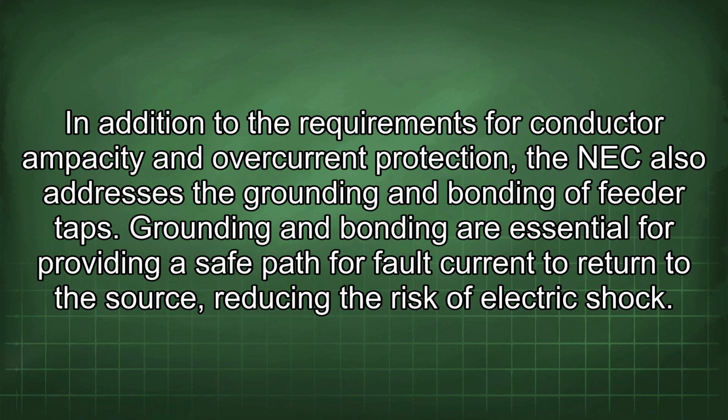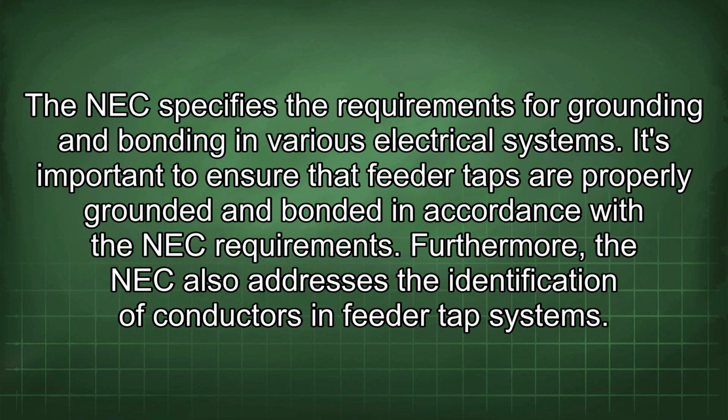application. In addition to the requirements for conductor ampacity and overcurrent protection, the NEC also addresses the grounding and bonding of feeder taps. Grounding and bonding are essential for providing a safe path for fault current to return to the source, reducing the risk of electric shock. The NEC specifies the requirements for grounding and bonding in various electrical systems. It's important to ensure that feeder taps are properly grounded and bonded in accordance with the NEC requirements.